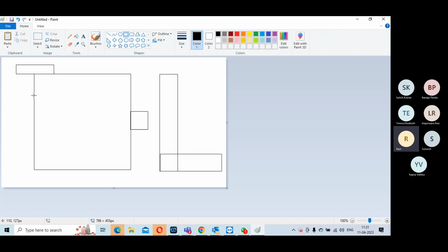So if there's a memory in module A, then that module A memory you can try and place here. Only if module A has macros will you try and position them. You cannot add module B's macros over here. That will be a problem, a timing problem will come. You are creating a module split, which is not acceptable.